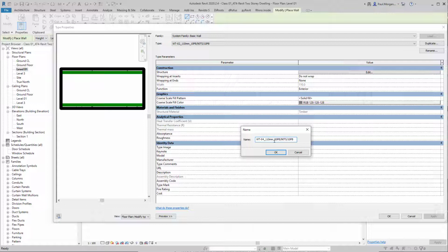So it's a 13mm timber cladding, TC, followed by a 35mm, which would be a timber batten, TB, or even just you can put in bat for batten, and then followed by a 90mm timber stud, and the 10mm plasterboard, which is still there. Okay.